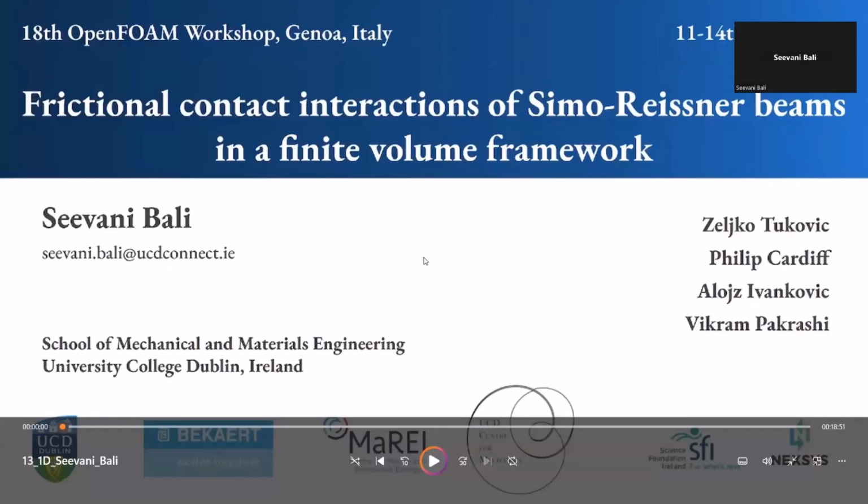Yes, I think so. The under relaxation helped a bit, but when I was trying to do the implicit corrections to the friction, I dropped out certain terms due to some convergence issues. But I think that if I add those terms, there is some problem with the implicit correction terms, is what I feel. Maybe if I change them, there will be a better convergence. Also, I think it's a large sliding problem. It's slightly dependent on the mesh, and that's why it's not really exactly clear what's happening behind the frictional jittering phase. But I think I'll look into it more. Mostly it's because of the implicit corrections, is what I reckon.